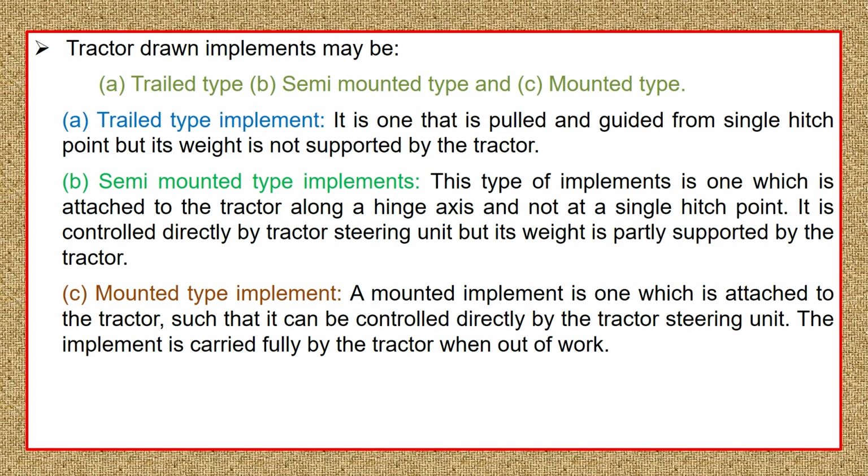As the tractor pulls, they start plowing, and as the tractor stops, they stop moving over the soil. Lifting and lowering them, or raising them out of the field or into the ground, takes place by a remotely controlled hydraulic system within the frame of the attached implement. That kind of implement is called a trailer type implement.